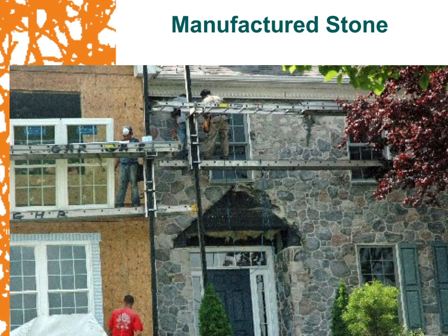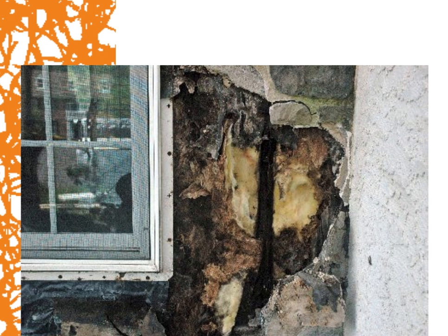You can see where the stone is discolored and darkened along the base of the windows and along the doors. But through that whole wall system, just like on the project to the left of it where there's just OSB, they had to peel off all that product, peel off all that wood due to moisture intrusion behind that manufactured stone. And in this next picture, you'll see a close-up, but again, the facade is hiding what's going on behind there. They started digging into it and noticed that there wasn't just a slight moisture problem, there was a huge moisture problem.